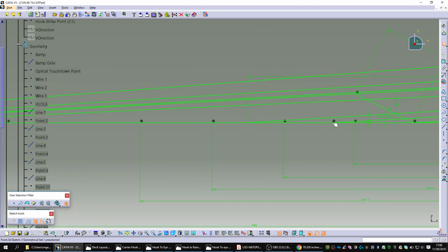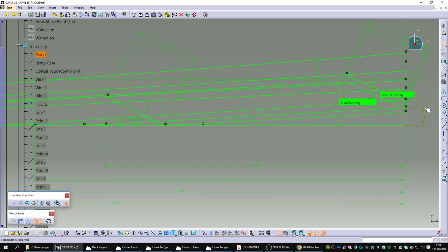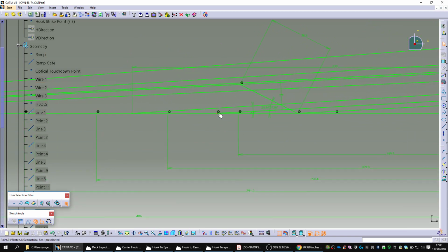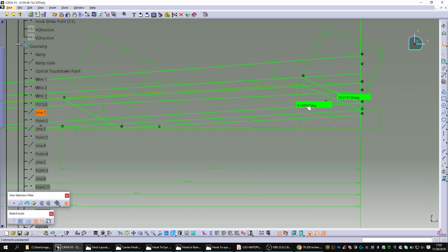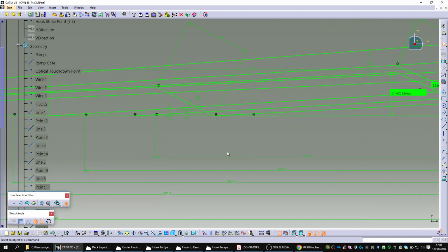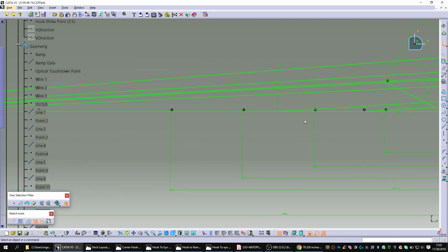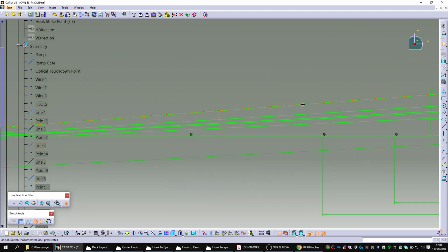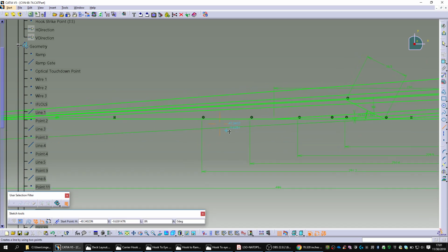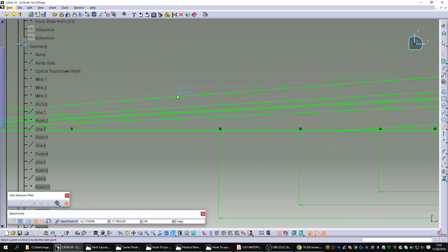Okay, so now we know minimum. Hey, if you're meeting the safety clearance of 10 feet over here, your hook strike's there, and it's a 3.125 degree meatball. Okay. I kind of took some tolerance off there. Now what happens if you ride a 4.35 degree angle all the way down? Holy cow. Now, the lines are getting crazy here, aren't they? But I think you can follow along.